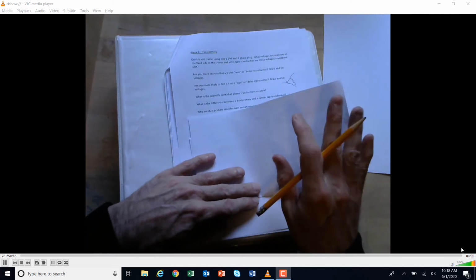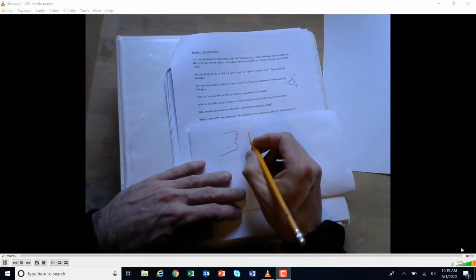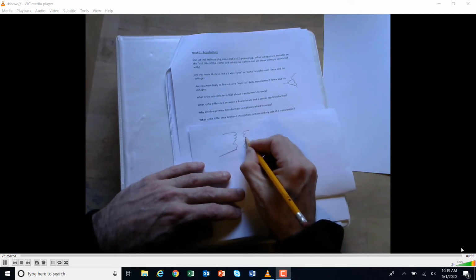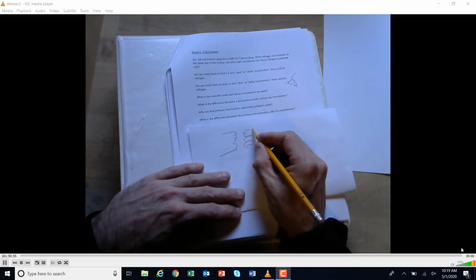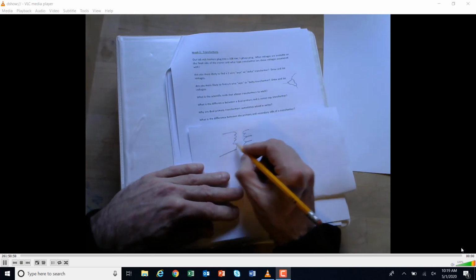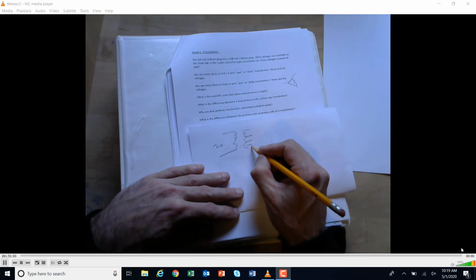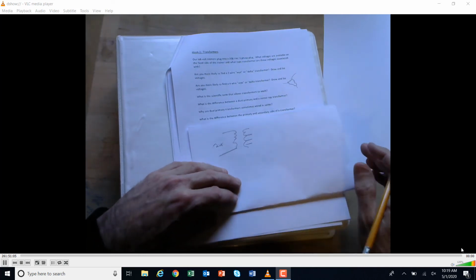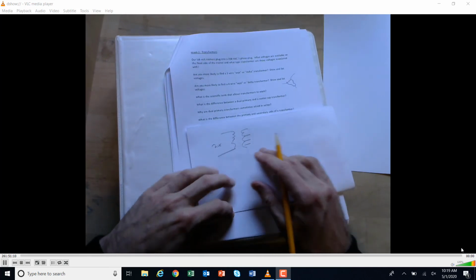The other one that we did on the Lab-Volt was the center tap. The center tap was where you had your primary here, and then your secondary had different voltages that were tapped off here, so you could get 40, 80, 120 volts on this side, depending on if you brought in 208 over here. So these were center tapped. You couldn't change them, you couldn't change them on the other one either, but you just picked off the one that you wanted. There was no jumper.